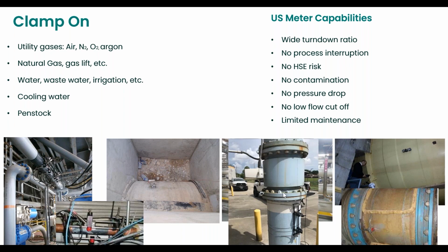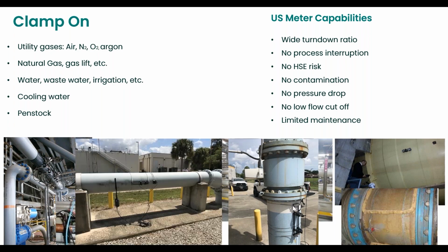This photo also is on a ductile iron. It's not an easy one, but you can see there's another flow meter here installed that is faulty, and we have clamped an ultrasonic to get a measurement, because this water is actually billed to another plant. So that's a water facility that is billing the water they send to another plant. This one is also a ductile iron installation. So it has been clamped there using a dual traverse setup.